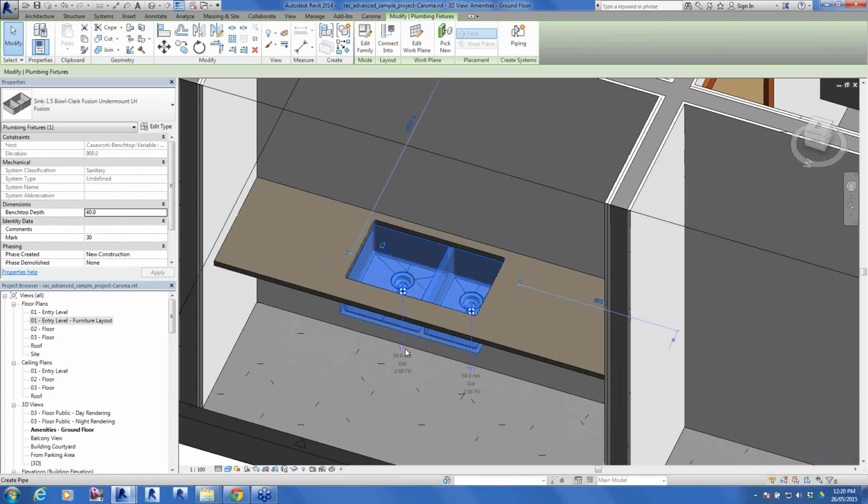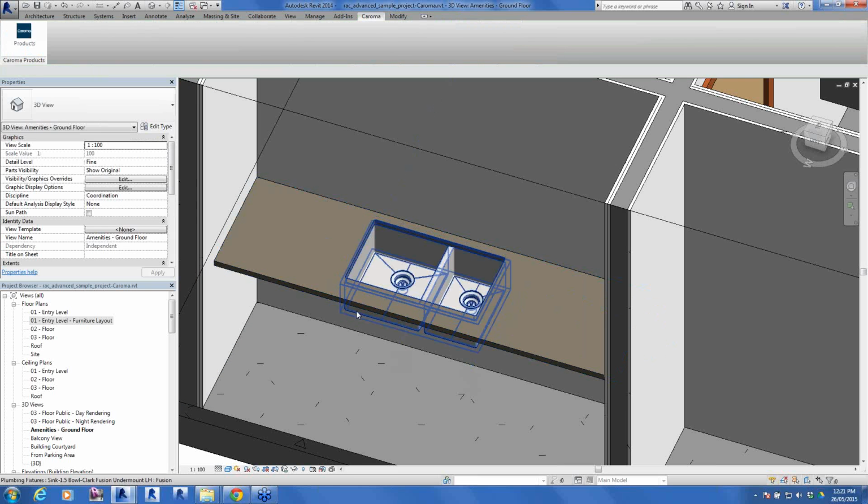We've got all our connectors, all the different waste outlets here. In this one, there's actually an instance option to specify the bench top depth. So if you have a particular thick bench top or a thin one, you can control where it sits in relation to the top of the bench top. This happens to be a 32mm thick bench.